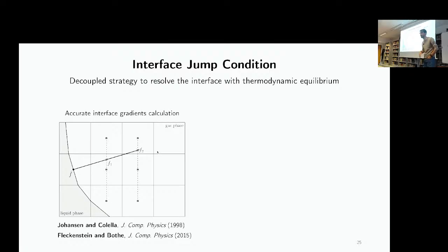And finally, the last ingredient, the last thing that we need in this model, is the calculation of the vaporization rate, which is non-trivial for multi-component droplets. While it is quite simple for boiling and also for pure droplets, for multi-component droplets it is not so simple because we don't know anything about the interface. We don't know the liquid mass fraction at the interface, the gas phase mass fraction. We don't know the interfacial temperature. Everything in principle is coupled in a nonlinear system of equations.